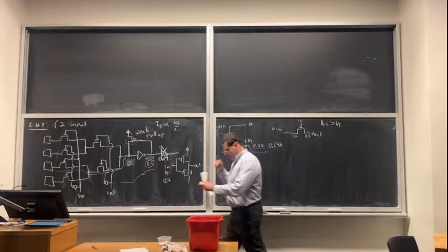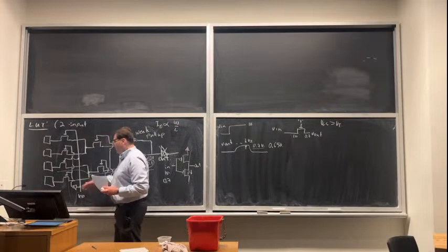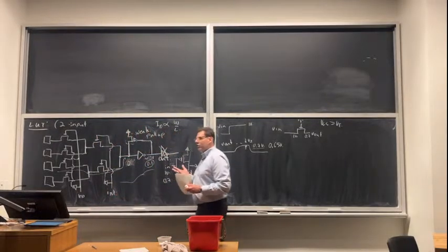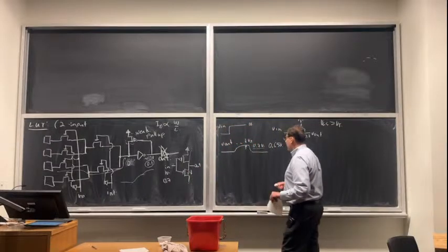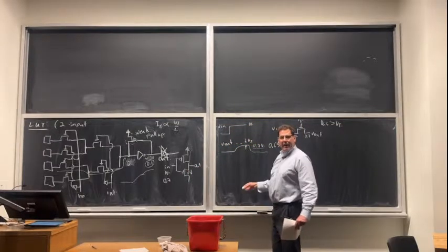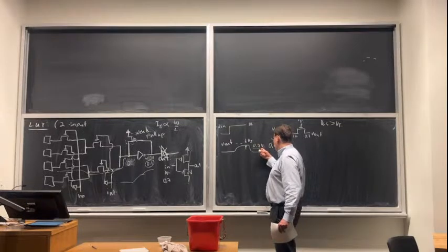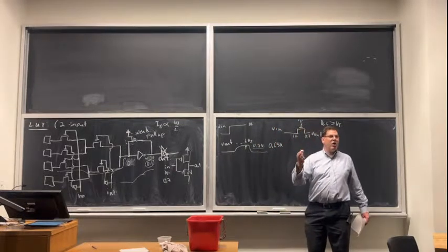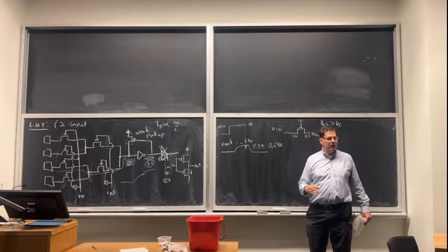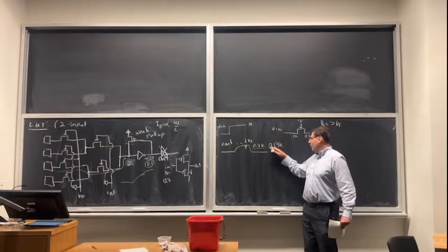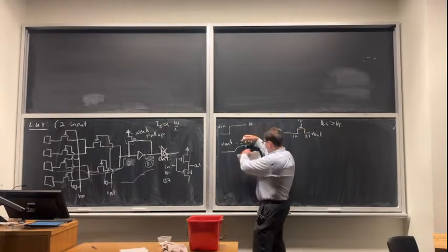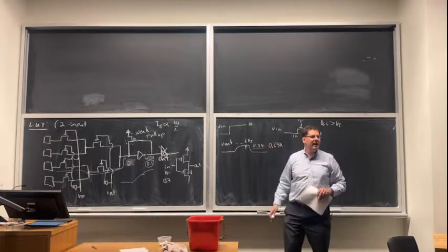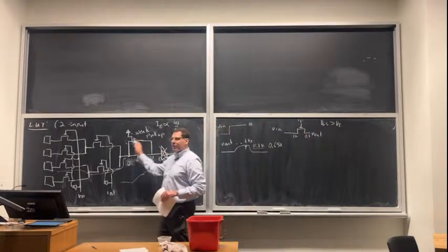Okay, so this is my lookup table. FPGAs usually use pass transistor logic for this. It's getting trickier because VDD keeps going down, and threshold voltages are also going down, but it's hard to keep them going down at the same rate. If your threshold voltage becomes a bigger part of your VDD, then this gap gets bigger, and that makes this harder to design.